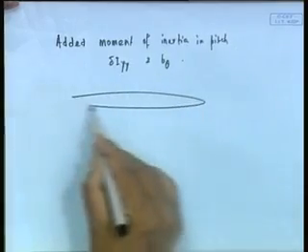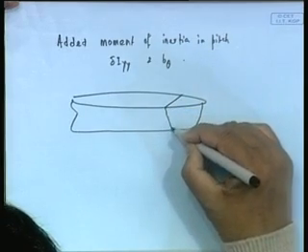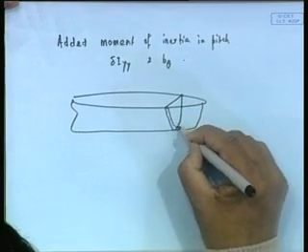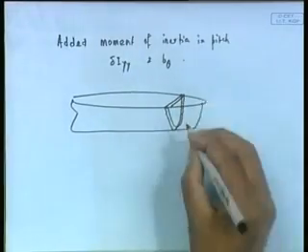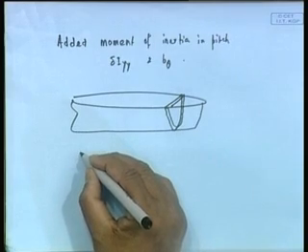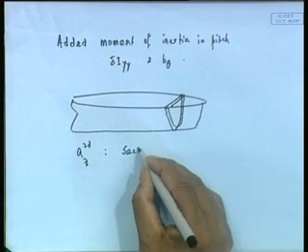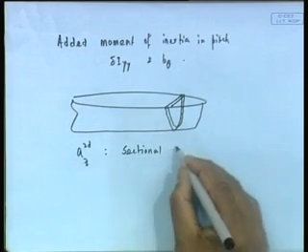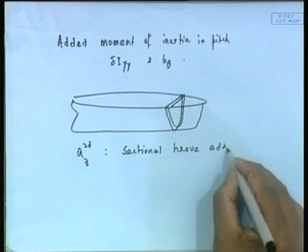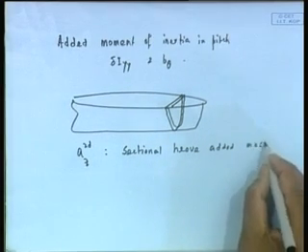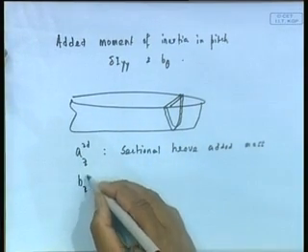See, just like heave, if I have this ship here and if I took a section, and if I have my sectional added masses, Az2d was my sectional heave added mass, and of course, we can also have that similar damping.